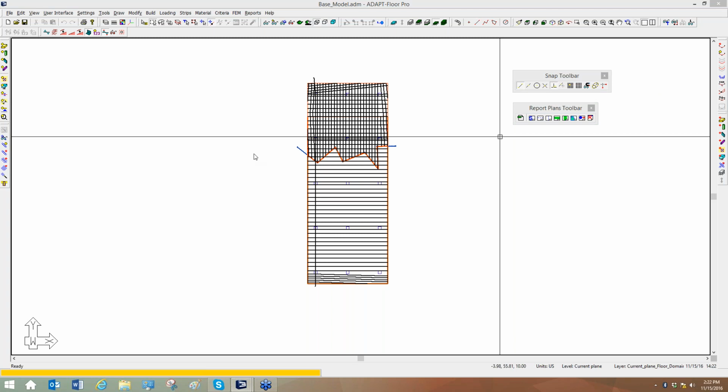It says, can it be summarized that the direction of the splitter is to be the same as for the support lines we are trying to limit or distribute the tributaries? Yes, that's correct, Pavel. To summarize, if you're trying to generate strips or manipulate strips using splitters, the splitter has to be the same direction as the direction of the support line.